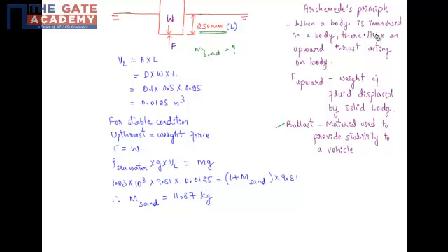So to solve this question, we'll use the Archimedes principle, which states that when a body is immersed in a fluid, there will be an upward thrust acting on the body, and this upward thrust is called the buoyant force, and it is the weight of the fluid displaced by the solid body.